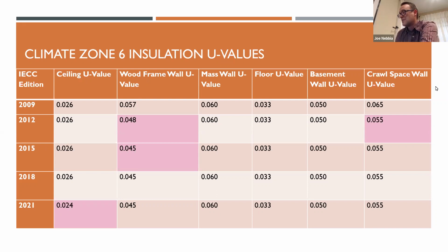And part of that is the compression at the eaves that will happen with an R60 bat. So that's something to keep in mind there. So if you're using U value compliance, maybe you're using a SIP wall, structural insulated panel, and that's totally continuous insulation. You've got a different U value than the R value listed in the code. Maybe you're using it for your roofs. You're going to want to use that U value compliance to meet the code instead of the R value, possibly.